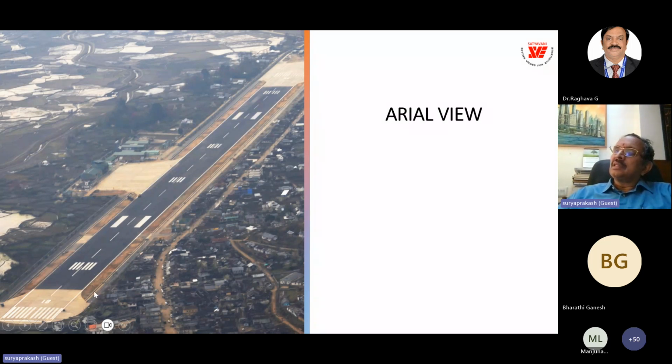And then they could not build a compound wall here, a security wall, due to this encroachment. Before inauguration of this project, due to excess rainfall there was flooding, and you can see the lake on the downside here. So this portion of the security wall has collapsed. What I'm trying to say is, even while we design the security wall, we have to study the overall topographic features and overall risk, and design accordingly.